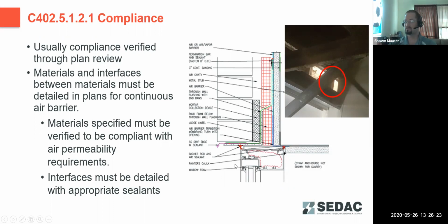Very important to detail, especially complex joints in your building, tight corners, difficult to reach areas. You can see in the example picture here in the red highlighted circle, there was a detail with a couple of closely set I-beams that got missed. And this allowed a lot of outside air to come into an open plenum ceiling area, and the HVAC system could not keep up with that additional load. And so they had a lot of comfort complaints and humidity issues in this building.